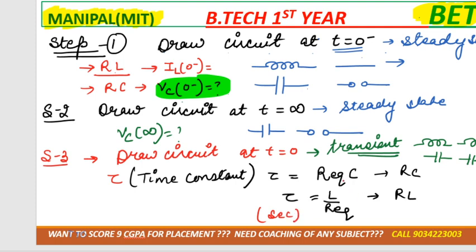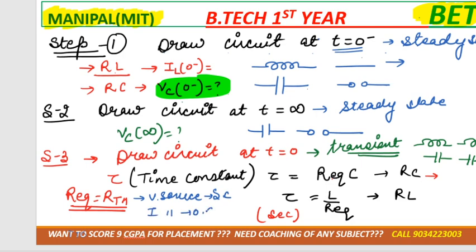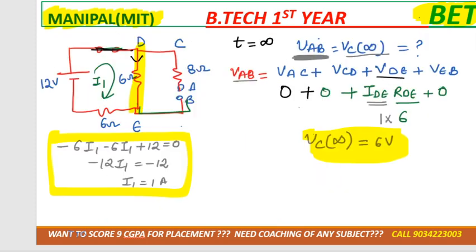Okay? R equivalent we can calculate similarly, as we have done in Thevenin, that is RTH. So to calculate RTH or R equivalent, we need to remove all the sources. If you remember the Thevenin theorem, a voltage source must be short circuited and a current source must be open circuited. Okay, now back to the question.